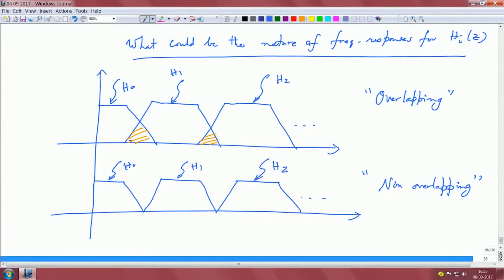So, therefore, you will get a clean signal. But if you think about the caveat of this structure, you will have to really design filters that have very steep responses, because you really have to notch and null them off at certain points in the frequency spectrum, right.